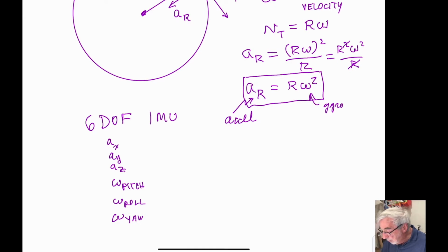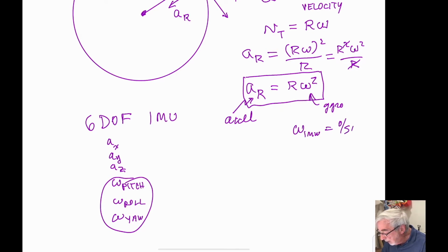You'll need to know how to convert this value for the measurement tool. The IMU omega is in degrees per second. We need omega in radians per second, so you need to know how to convert that. One complete circle has 360 degrees, and that's the same as 2 pi radians.